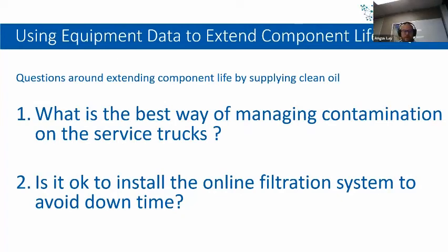No, I think you definitely covered it. The only other area is good housekeeping. A potential source of ingress is obviously the coupling. So it's always good to do spot checks and ensure that the service truck operators are aware of the criticality of keeping those Wiggins fittings clean and capped when they're not in use, and not just laying around the bottom of the box with the rest of the fittings with oil, dirt, water and muck floating around. Your oil might be cleaning your service truck, but are you contaminating when you plug it into the actual vehicle when you're doing the oil change or the top up?